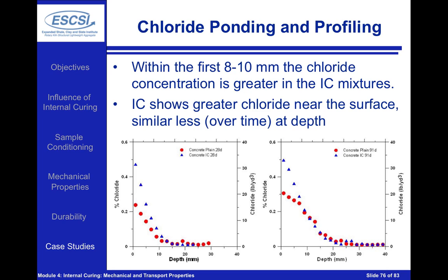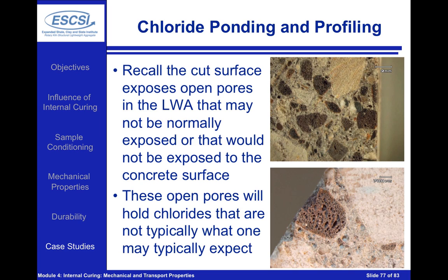However, as you get further away from the surface, getting down toward where the reinforcing bar is, what we typically see is a lower amount of chlorides, and at later ages, we'll actually see that this becomes even less than a plain concrete in the overall system.